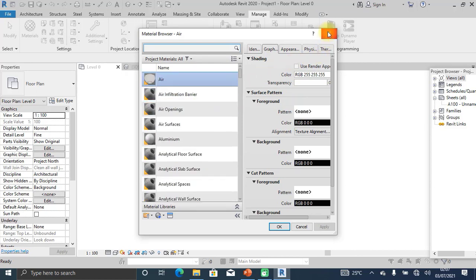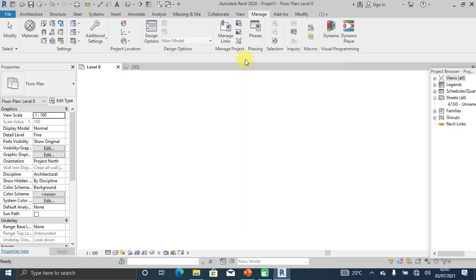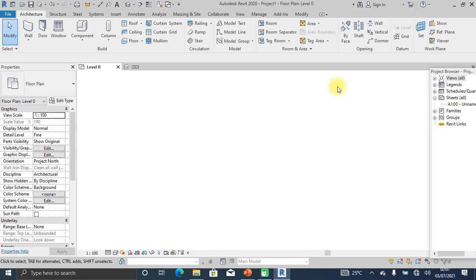When there is time for material application in a whole topic, we'll discuss that. So we are coming back to the architectural tab. Now you see that the toolbars are organized here in kind of a sequence. So basically, when you first start your architectural design, there are chances that you have to first do your building using this building component. Then you can go ahead and do stairs and so before you start thinking about some modeling in rooms. And then you see that you can create openings and datums and so. So they are organized in this kind of a sequence.